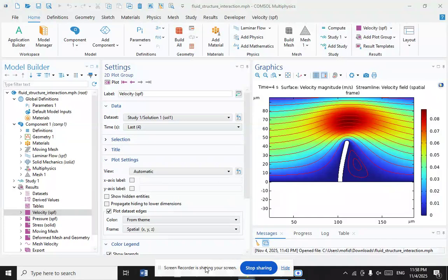It is also possible to reformulate a fluid structure interaction problem as a system with only the degrees of freedom in the interface's position as unknowns. This domain decomposition condenses the error of the fluid structure interaction problem into a subspace related to the interface.